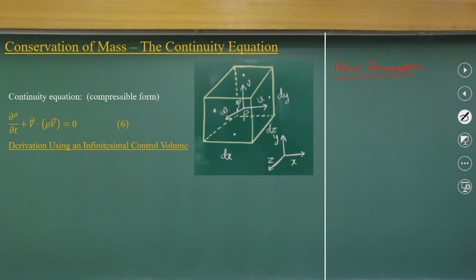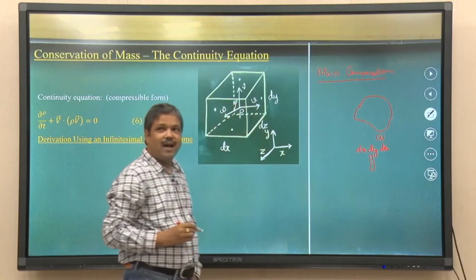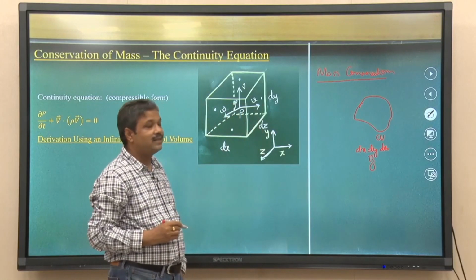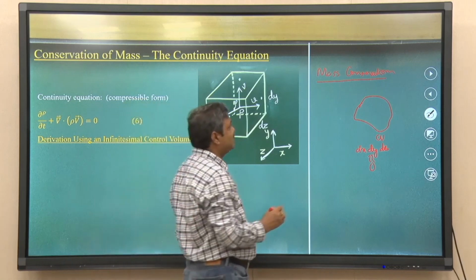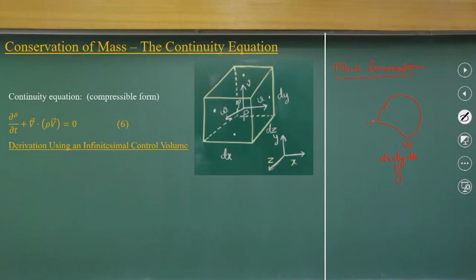As we discuss it, that means the control volume dimensions dx, dy, dz are very close to 0. So, when you have infinitely small control volumes, we are looking at how we can have a differential equation format for the mass conservation equation.